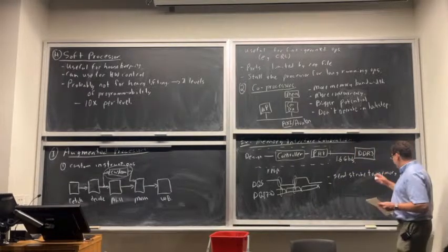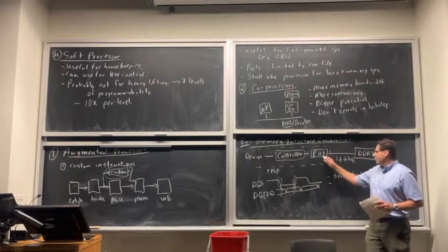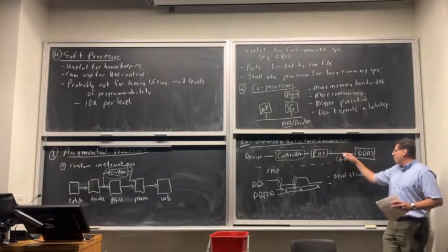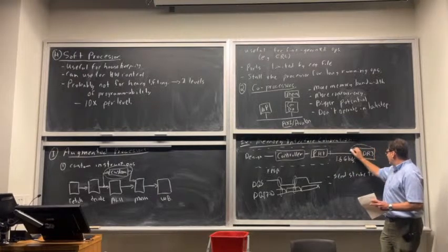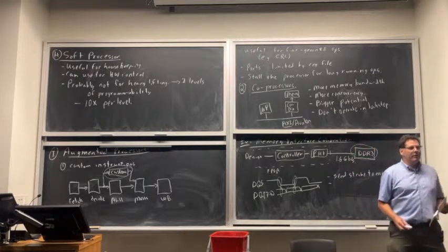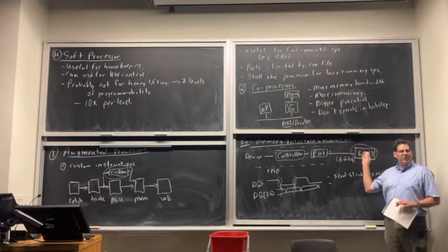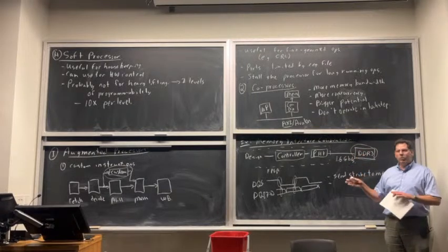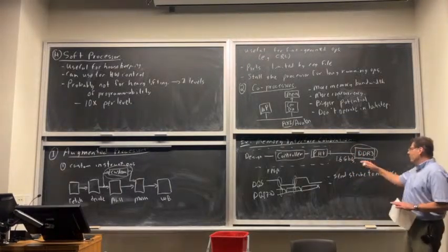Okay, so the challenge is that basically, once you account for voltage fluctuations, temperature variations, board mismatches on the signals, crosstalk, and DDR chips are made to be cheap. So their specs on their timing are actually pretty loose. Like these chips have variation in their transistor manufacturing. So they have like a window of how long it will take them to sample the data and so on. And those windows are pretty wide.